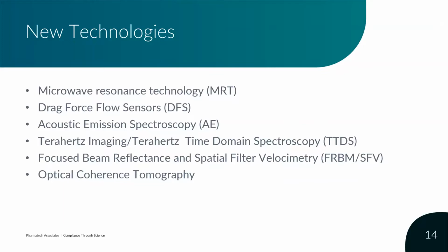And then that light, that backscatter, as it passes through, can be used to determine the chord length of particles, which is really a fundamental measurement of particle size. And in a very similar manner, they're almost inversely related. Spatial filter velocimetry also provides particle size information, but in this case, it's the shadow of the particle that passes through the laser that determines the chord length. So that's more of an indirect, but still valuable